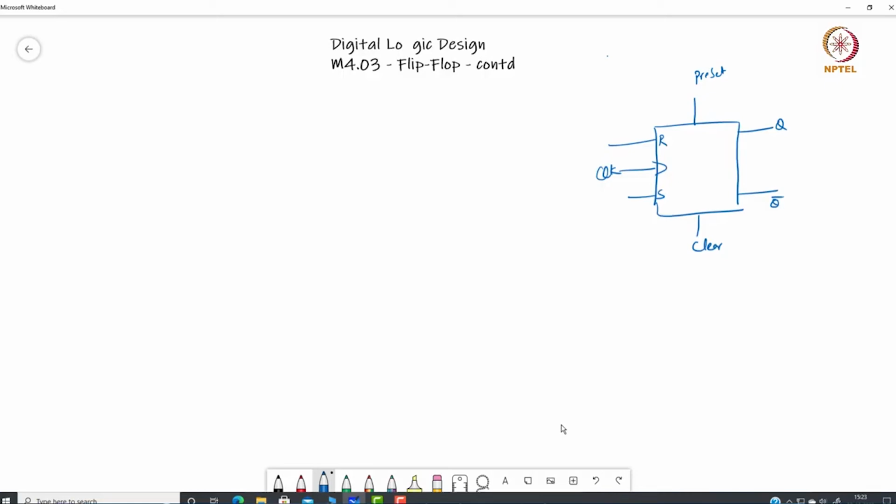Usually you will see that most hardware has a small reset pin. In any hardware, you will see at least one reset pin, which ensures that the starting operation is clear, initializing all the memory elements to correct values. This reset pin has to be independent of the clock, because once the clock comes into the picture, the next value will depend only on the synchronization point.